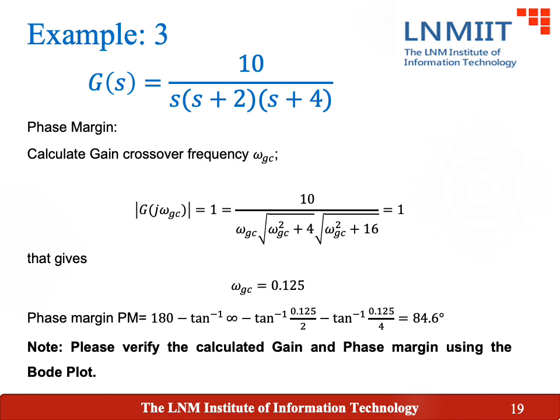So this is for today's lecture. I will leave a few assignments for you. You have to verify, for this particular transfer function, with the help of the Bode magnitude and phase plots, that the gain crossover frequency, phase crossover frequency, gain margin and phase margin are the same or not. So take the help of semi-log paper, sketch it and find out.